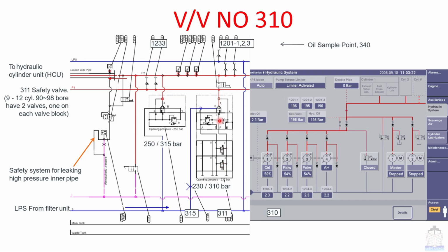As I explained before, if I depressurize this part, then this main valve opens automatically and hence all pressurized oil will drain out through port number B. And this depressurization of the oil is done by three methods. The first method is by the hydraulic oil itself, which activates this pilot valve and hence this main valve opens. Another method is by these two solenoid valves. These two solenoid valves work in parallel.